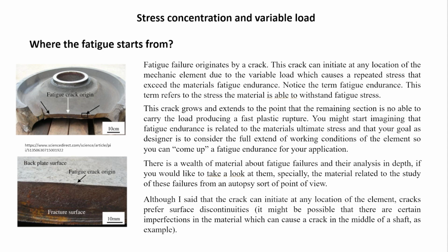Then, where does fatigue start? Is there something that we could do? Well, yes, as I mentioned, fatigue usually starts in a small crack, a small micro thing, usually on the surface. We say usually on the surface because the surface is exposed and prone to these beginnings. And usually the maximum stresses are found on the surface when you calculate something. Let's remember the example of the beam or this rounded bar in the evaluated exercises concerning failure theories.